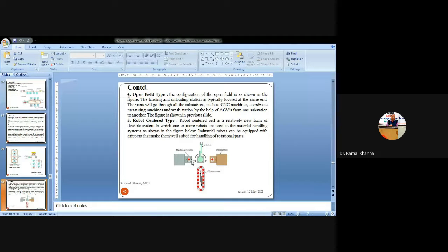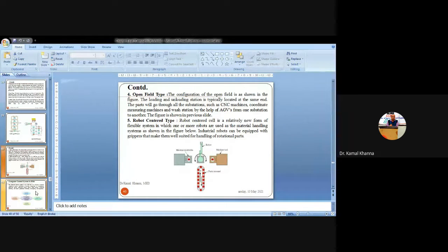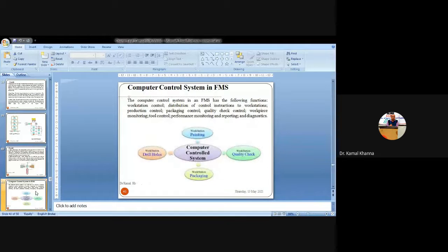And this is the line of parts on which the operation has been performed. The robot is getting the parts on this line and feeding the part to the first workstation, and after the operation has been performed, it fetches the specimen from the first machine and then feeds that specimen to the second machine. And again, whenever all the operations have been performed, the robotic arm puts the processed part onto this part line so that it can be transferred to the storage and retrieval department or the next shop floor, so that other operations can be performed or it can be stored or packed at the other department.